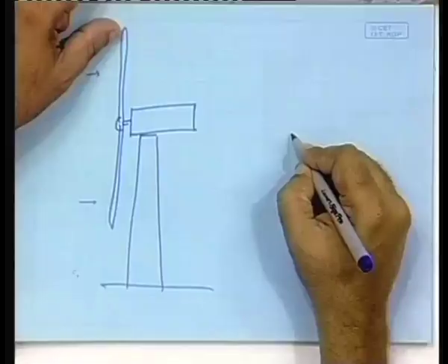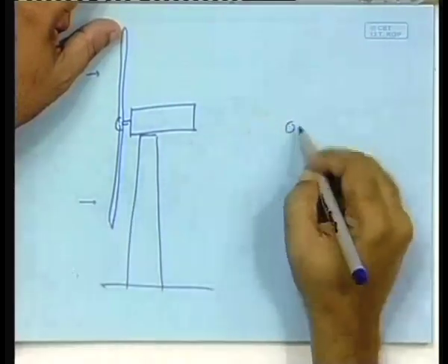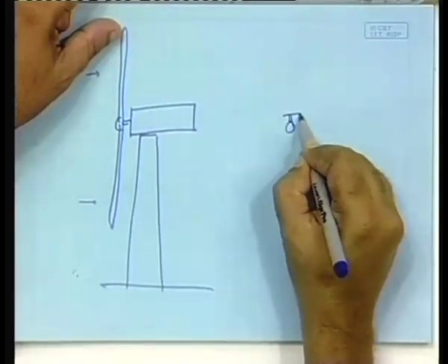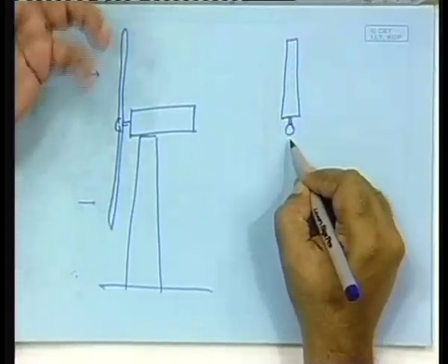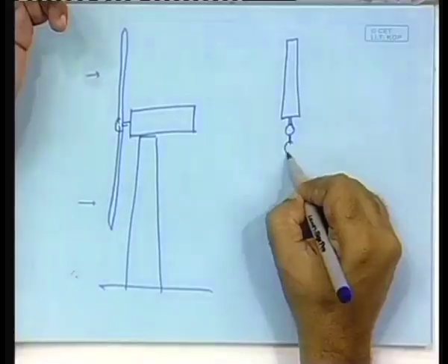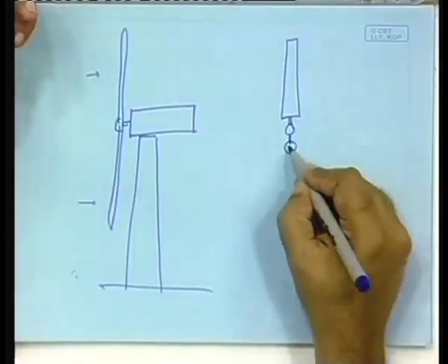We will later see that there are advantages of going for even higher speeds, very high speed rotors. In that case, you might argue that why not one blade? Well, there have been rotors constructed with one blade. That means, I am showing the frontal view, it is just one blade, and the other side has to be balanced. So, there is a counterweight, that is all.